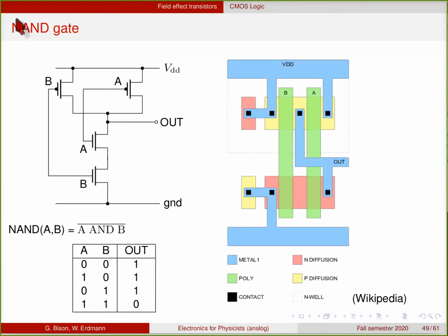This is called a NAND gate, and this shows a possible layout for a NAND gate. So you have the 2 NFETs shown here at the bottom, in basically the same substrate here. So this node here, which has no connection, is not even contacted here, of course. So the gates can just follow each other in the same tub, and the output node here is also connected to the point between the 2 transistors for the PMOSs up here.